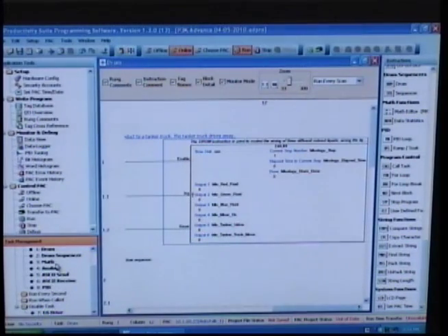During troubleshooting or debug, I can take any of the things I'm trying to do and, instead of running them at the full rate, if for some reason I want to run them slower, I can run them every second. I can run them when called, so I can actually do like a subroutine and drop some of my routines or tasks within the run when called and call them from other parts of the program. And I can also set up parameters, so when the CPU is first brought up in run mode, I can have certain tasks or ladder logic run for the first scan only.